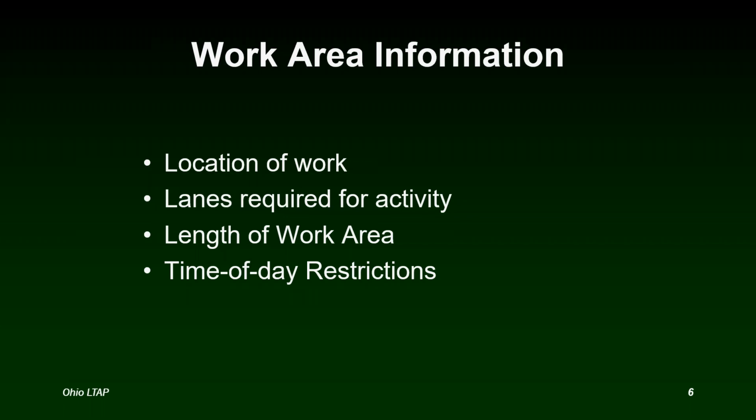It could be the location of your work. Where are you working that day on the road? Not just what street and where on the street, but also the location of your work within the right of way. So like, are you outside of the shoulder, not even on the road, or are you on the shoulder only? Are you on the shoulder but maybe a foot or two out in the through lane? Or are you in a through lane of traffic or two lanes of traffic? And all that information is tied to a different typical application.